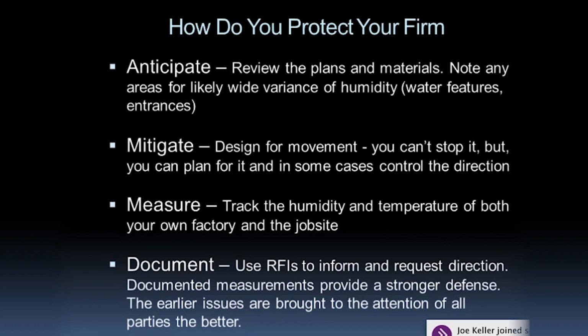Because if your factory is controlled and you have the humidity right there, but you're moving it into an area that doesn't have control, you want to make sure you get that conditioning time in that location. Now, I know, again, that's difficult, but I know there are times that the general contractor is telling you, deliver it today and start installing it immediately, and you don't have that time, but you want to try your best to get that time to allow it to acclimate to the job site.